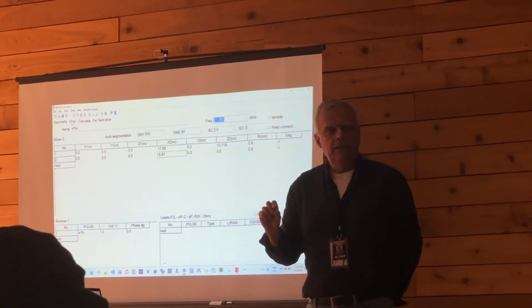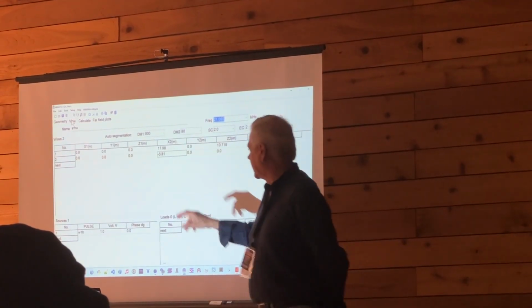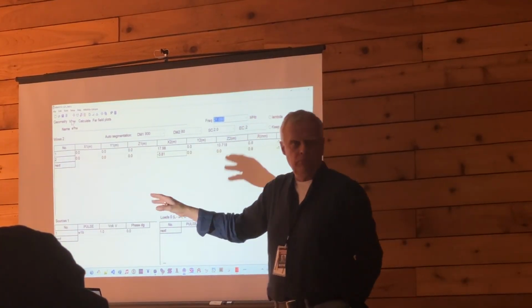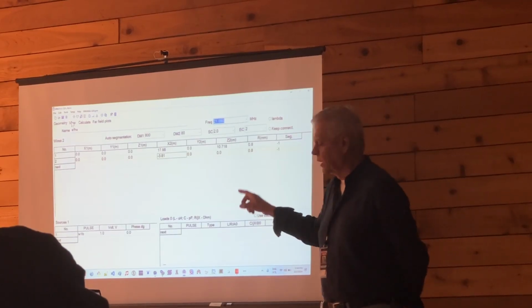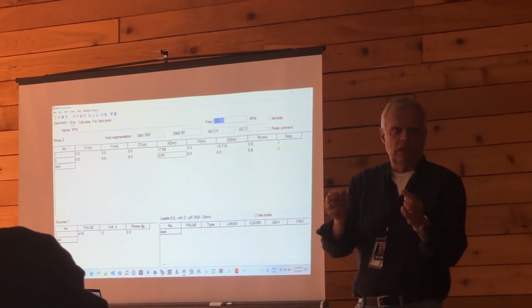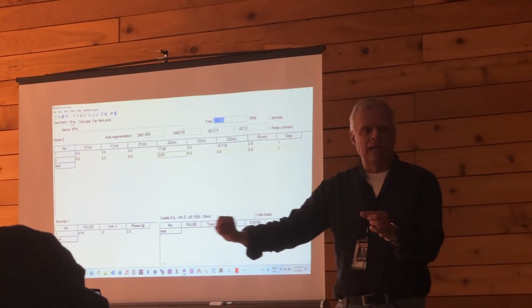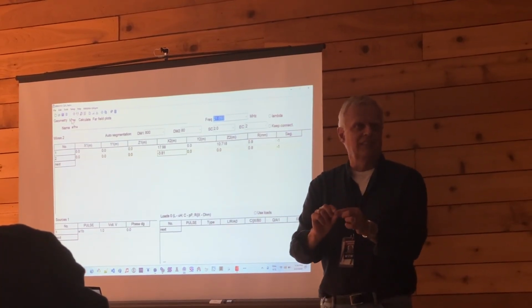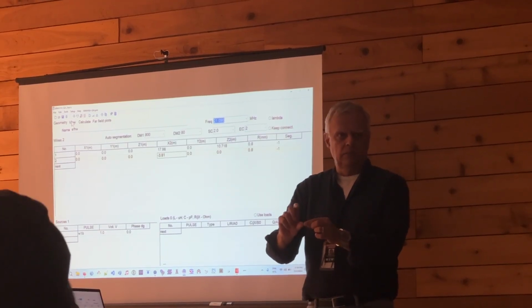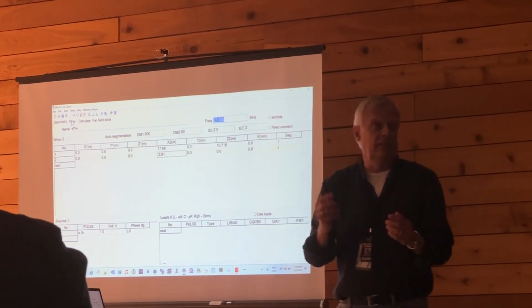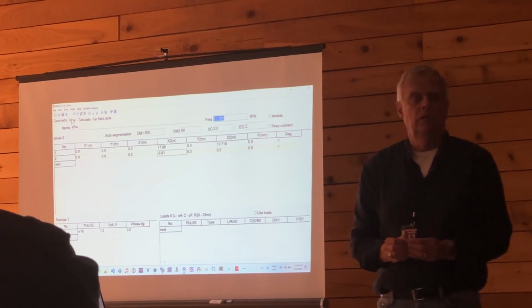I did mention AWG gauge, and by that I mean we're modeling 0.8 millimeters. But for our pigtail, I was using the coax, and the outer sheath of the coax is exactly what you're pointing at, and you're spot on. The LMR 400 might be a different diameter than the RG8X or whatever.